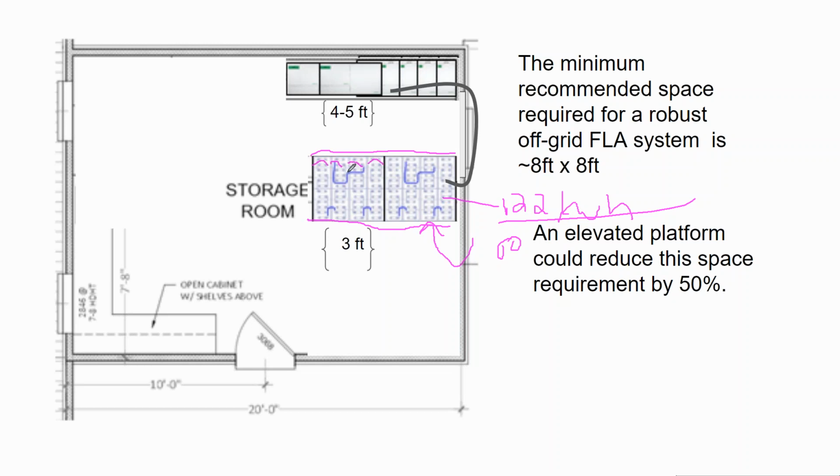But if you wanted to build an outdoor battery box and put all of your equipment in it, you'd be looking at maybe 4 feet for a small battery and 8 feet for a large residential battery, and then giving yourself another foot to build and mount your inverter and charge controller equipment.